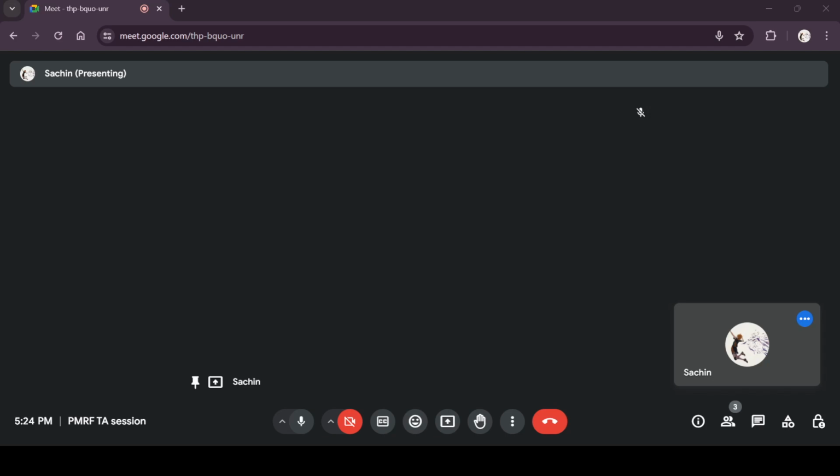That means, for example, Y0, you can see that M7 is connected to a diode, M5, M3 and M1 are connected to a diode. So Y0 will be M0 plus... Sorry, this is M1, right? It is M1 plus M3 plus M5 plus M7. So it's sigma 1357.